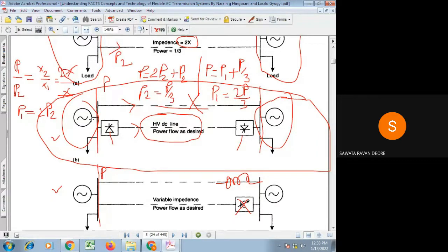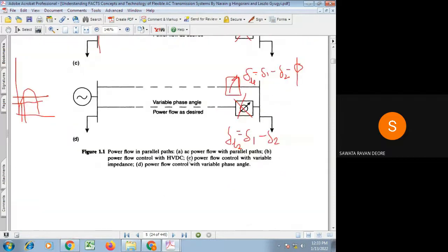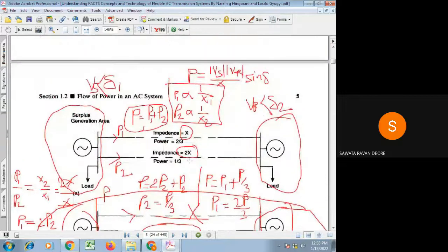And for an asynchronous intertie, if you want to operate both regions independently but want to do some fixed amount of power exchange amongst them, then in that case only the HVDC interconnection has to be done. Because the ordered power, that we can regulate through that DC link. But if it is paralleled by AC, then in that case, that control of power from one region to another region will not be there. So this is about the parallel operation of AC transmission lines.